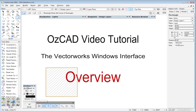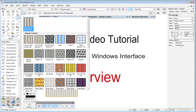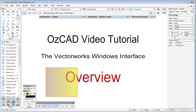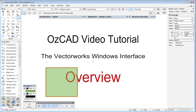For example, a hatch, a tile fill, and once you've chosen the tile fill or a hatch or whatever, you can choose the particular one that you want from the menu beside that. Gradients, image fills, and so on. We can also control the line thickness and line style here, so if I give it a thick line weight, you'll see that the line weight will fatten up.